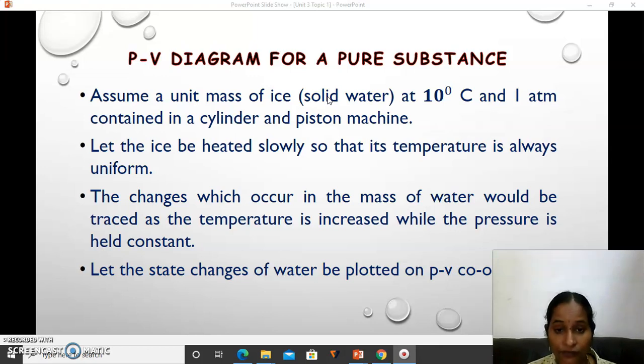Air, which is a mixture of 79% nitrogen and 21% oxygen by volume, can also be treated as a pure substance if the composition does not change when it undergoes a cooling, heating, expansion or compression process. We call air a pure substance since wherever you check, you get the same combination of nitrogen and oxygen by volume or by mass, uniform in its chemical composition.